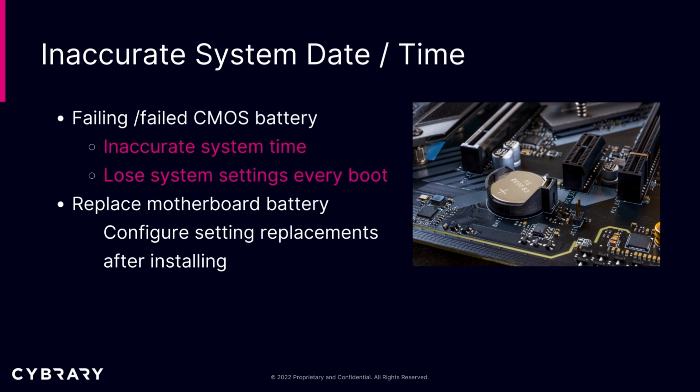Replacing that battery is very easy and straightforward. Check the manufacturer of your motherboard. The majority of the time, that battery is like a coin battery on the motherboard, and your manufacturer's information shows you the steps on how to replace it.